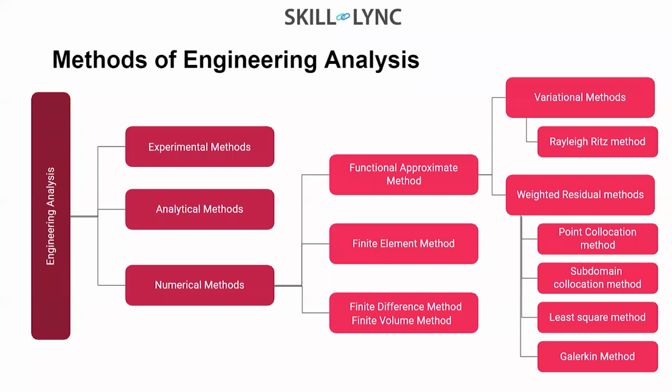So basically you'll have to use formulas such as, for example, in the cantilever beam, the deflection formula is going to be PL³ by 3EI. Okay, and then similarly you're going to use the bending equation to find out the stress. So based on all these predefined formulas and theorems, if you find out the results, that is what we call analytical results.